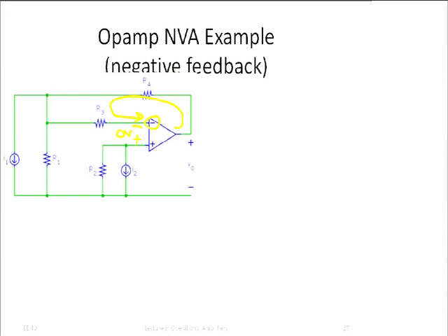Now you can analyze this circuit again in any one of a gazillion different ways. One of them is node voltage analysis. When we use node voltage analysis, we have to figure out which equations to write. So let's go through that. There is a slight modification to the general rule in this case. Again, we have to introduce a common node. We always have to do that if we use node voltage analysis. What's the next step? Yeah, we have to label all the node voltages that we don't know.